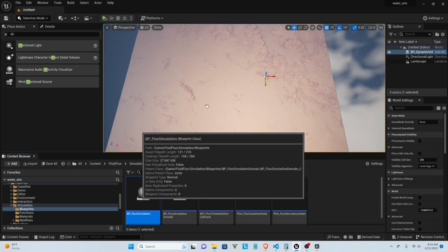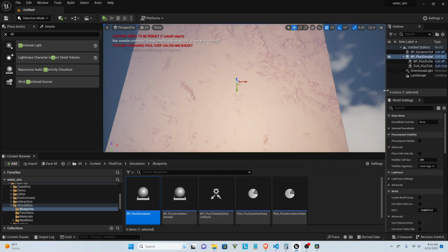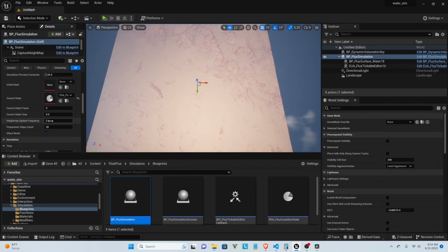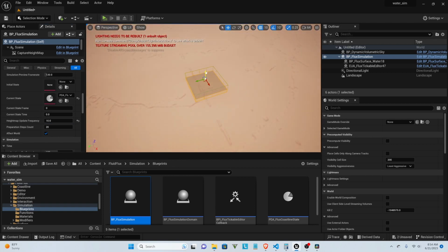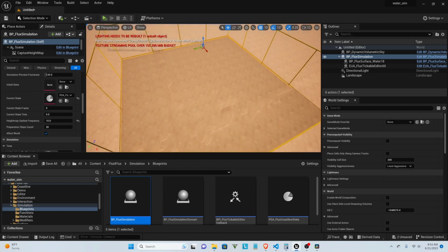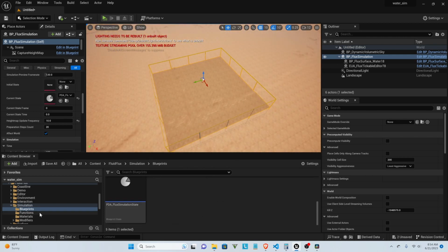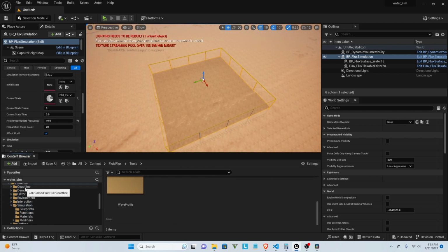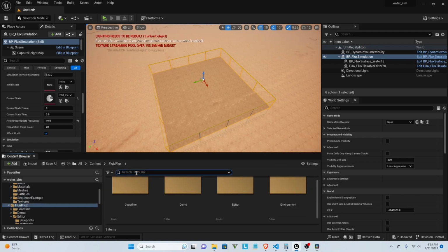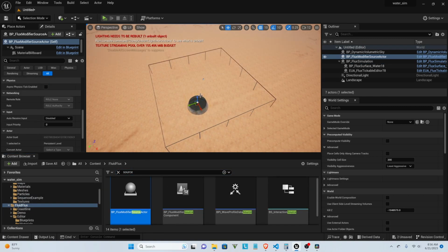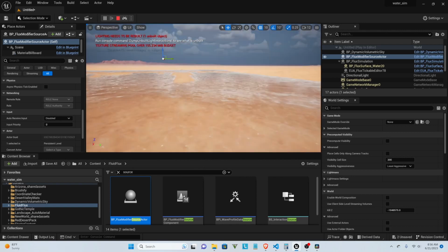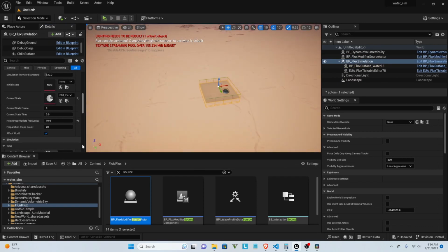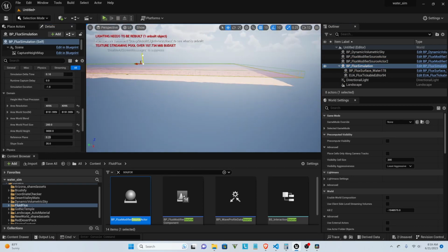And then I added the FluidFlux simulation. I found that getting this started in a small square first worked the best. Unless you have a supercomputer, I would also update the height map frequency to be something greater than 0.4. The simulation should stretch vertically around the entire landscape with a little bit of wiggle room on top or bottom. Then add your flux modifier source, and make sure it works in a small square before you move on.